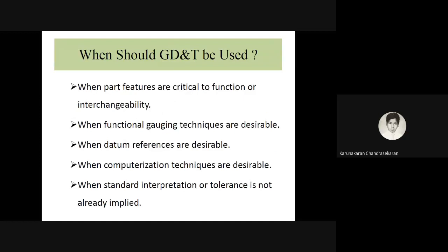And because of this GD&T, you will have more advantages and standardization. Why should we use dimensioning and tolerancing? Why is it necessary? For interchangeability. What do you mean by interchangeability? A component that is designed, represented or manufactured should be acceptable by another manufacturer or designer. So here you have a small hole drilled.